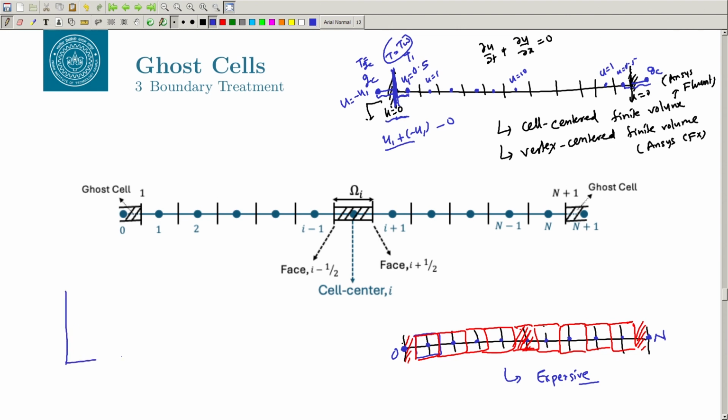If it is a 2D flow, let us say this is a 2D flow and you have cells everywhere, you construct ghost cells across each cell, which looks very similar, and the values of these ghost cell centers will be used to compute the value at the face, because the values are stored at the cell center only. This should be exactly the mirror of that.